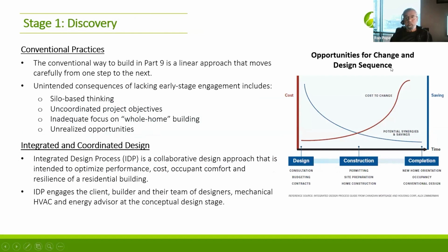So let's start with the discovery. Usually, as I said before, we'll do things in residential construction in a linear way. You don't call the HVAC contractor until the building's up, which is way too late. You want it when you've got the idea for the building, at least the HVAC designer, at the stage where the decisions you make are going to impact what you build. You want that up front, not as you go.